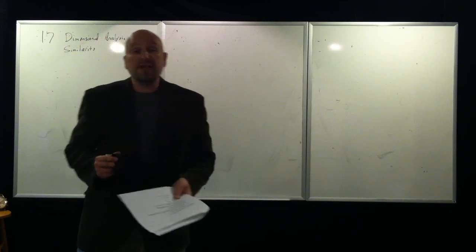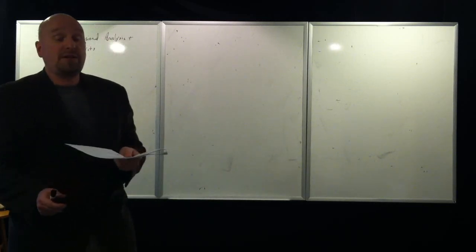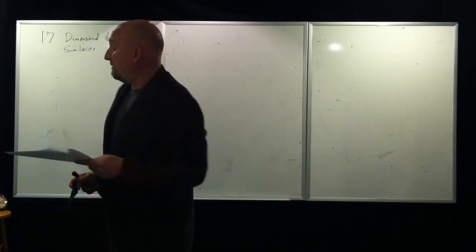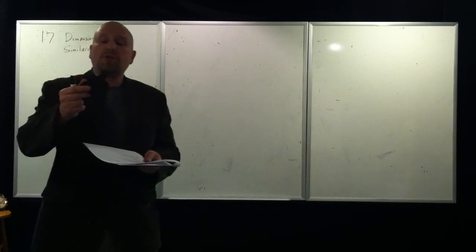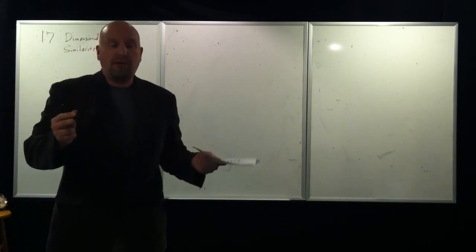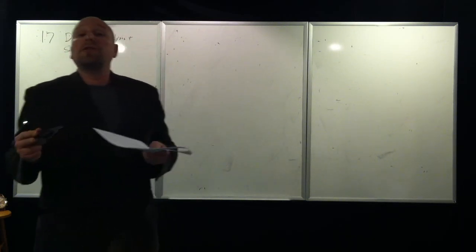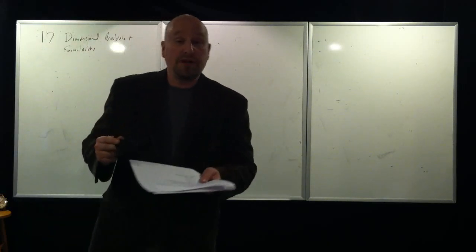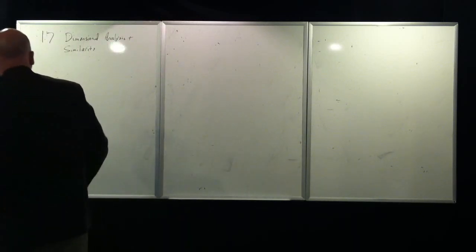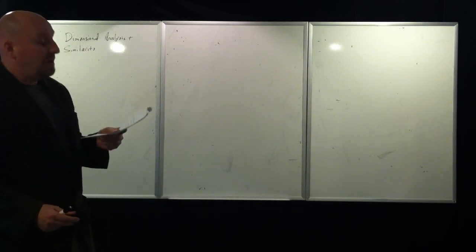There are important parts of dimensional analysis and similarity which we're going to go into. We're just going to briefly touch upon some of the power, ability, and flexibility that dimensional analysis has. It's much easier to work with a model that represents all the important geometry of the prototype, the real physical apparatus you want to use, an airplane or a submarine, represented in different non-dimensional coefficients and numbers.